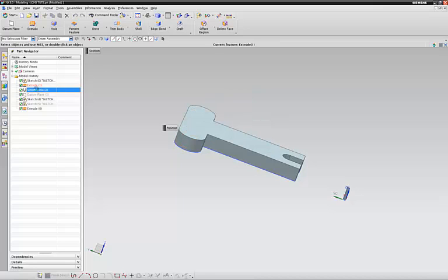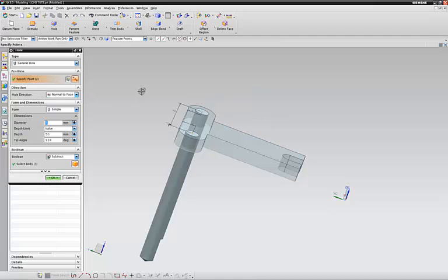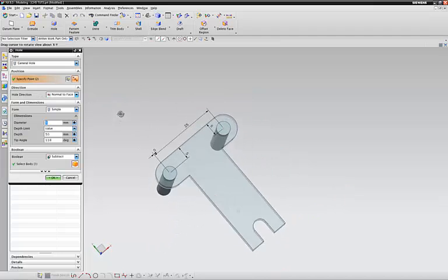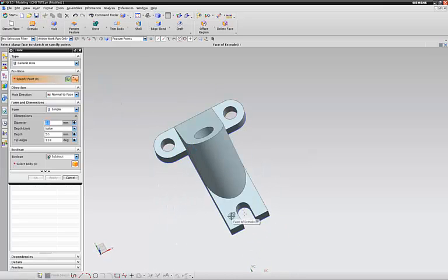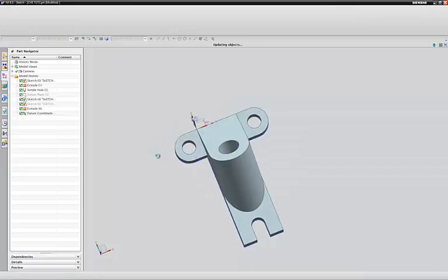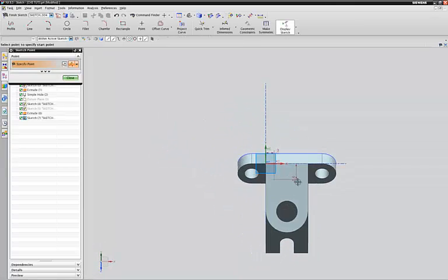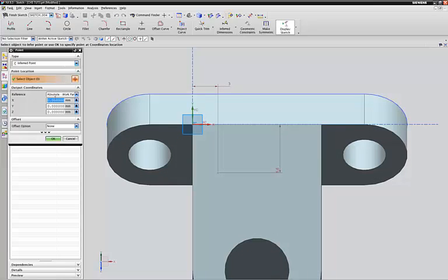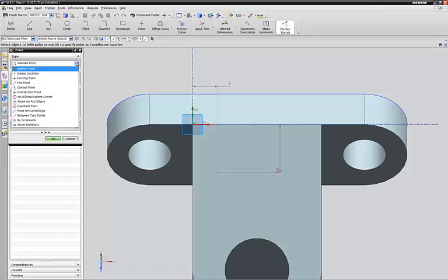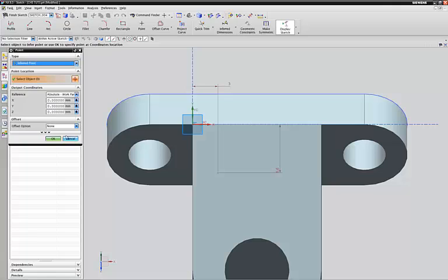Then the next step was this hole command, which when you create a hole, you pick the plane or surface you want to create the hole on. Then it takes you there and it specifies the point of this location. You can do that here, by giving it coordinates if you know what the coordinates are. You can also choose other locations as you see fit.